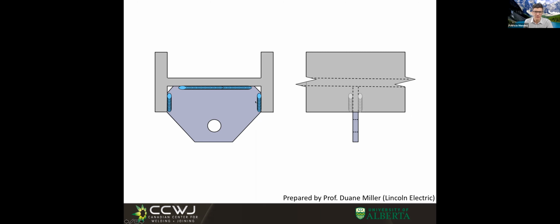These two welds on the side, those are against something very stiff, right? And because now it's stiff because it's the web, the flange being vertical, they became stiff. But are these welds long enough, right? So let's not do this, right? Like the load is coming through these little parts. So that weld didn't matter. So we can take it out. But is this strong enough?